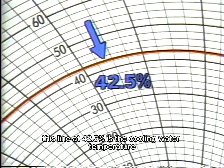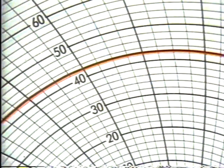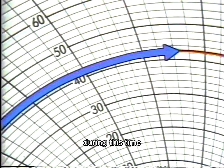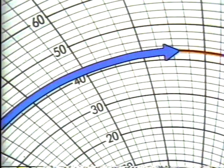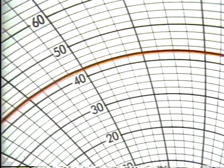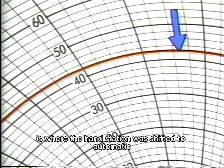This line at 42.5% is the cooling water temperature. It's right at set point. During this time, the system was in manual and there were no load changes. Right about here is where the hand station was shifted to automatic.